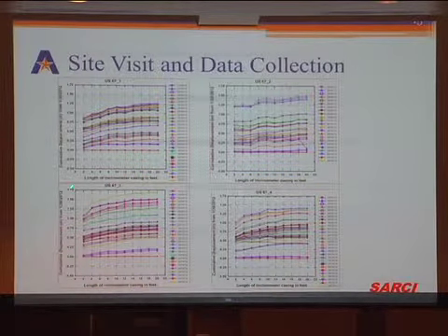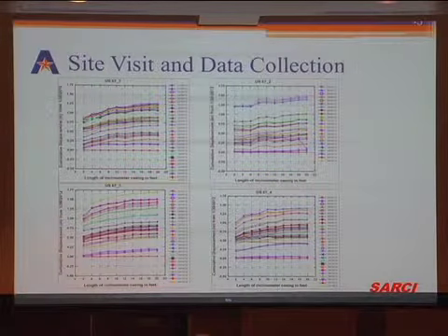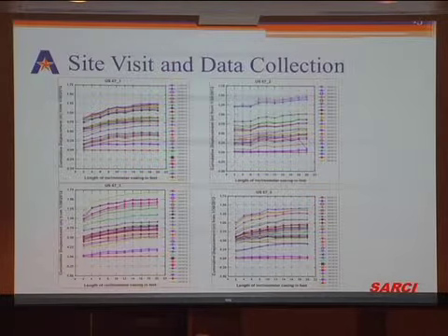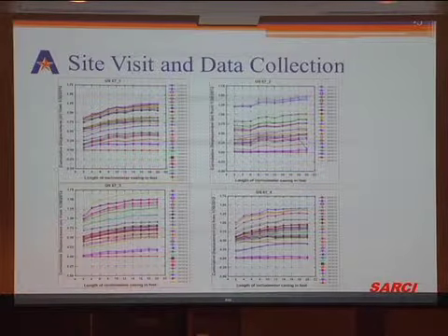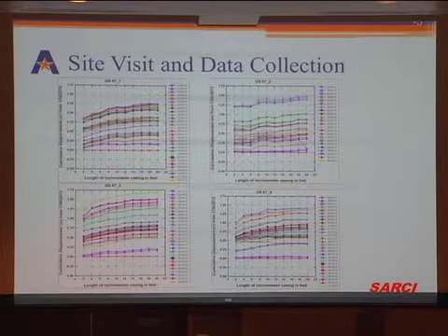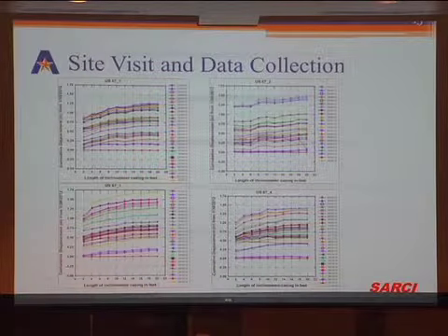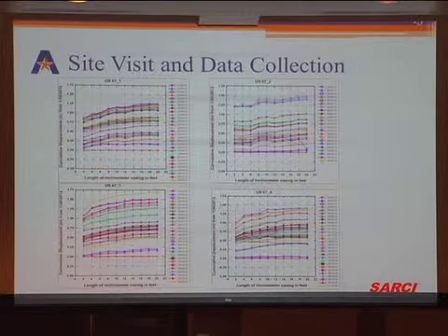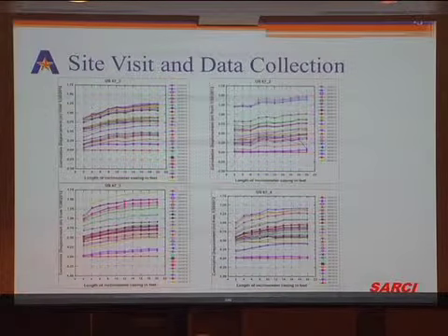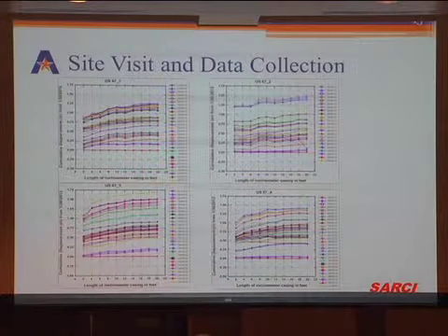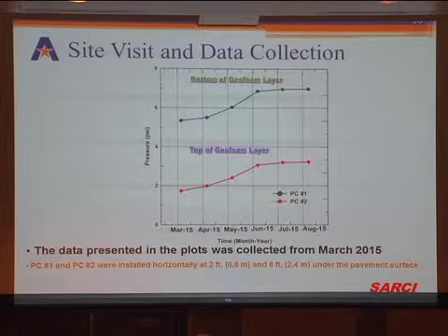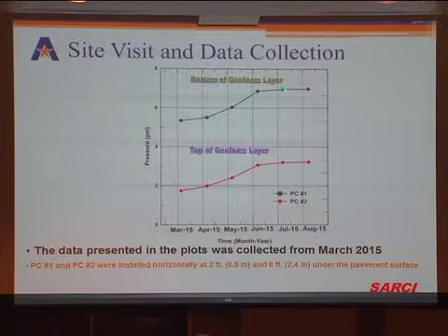We do have some settlements in this particular section, as you see with time. Some of the settlement came during construction, because when you place the foam, you still have to place the upper base layer, and then you have to put your concrete pavement. So that was actually covered up. There is some construction settlement that was induced and collected by our instruments. And then over time, after it was open to service, we collected settlements also, which is shown here in this data. The pressure cells showed, again, the two pressure cells that we picked up here at the foam level,